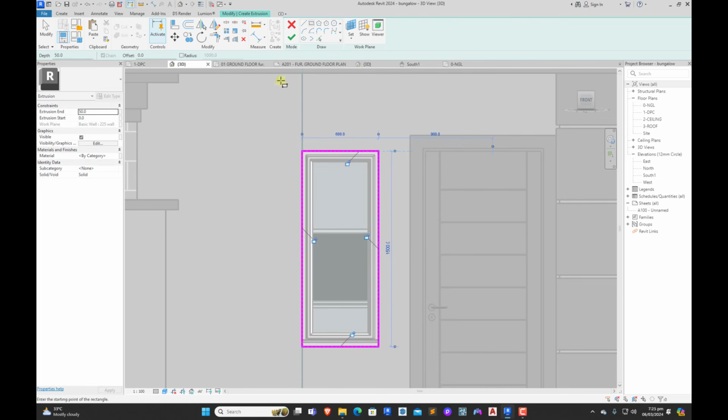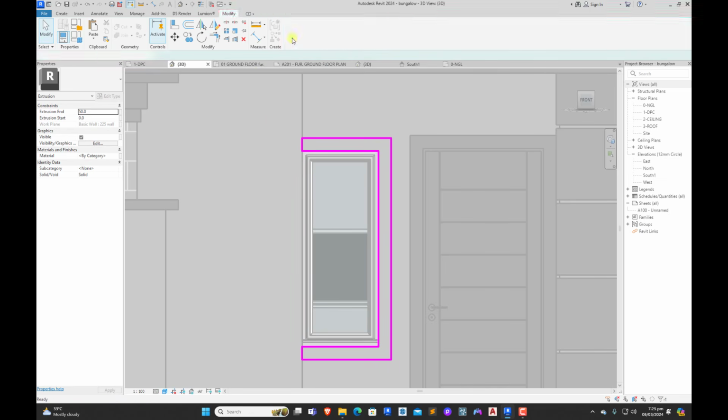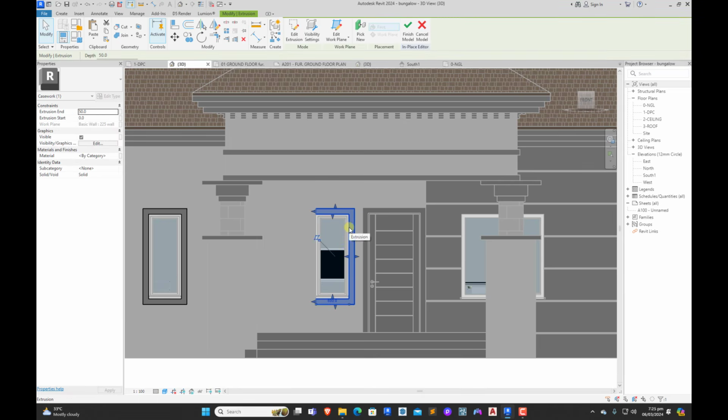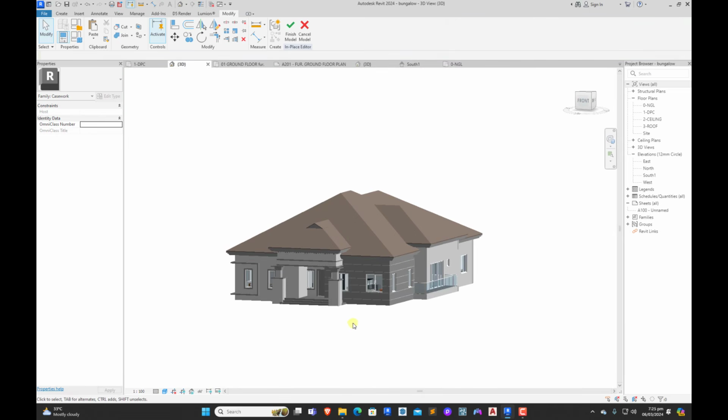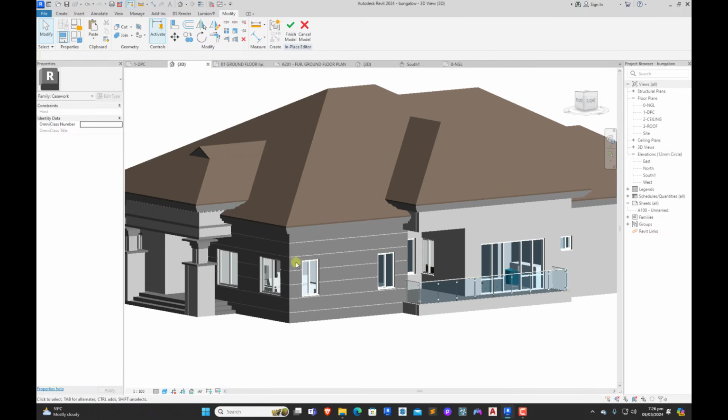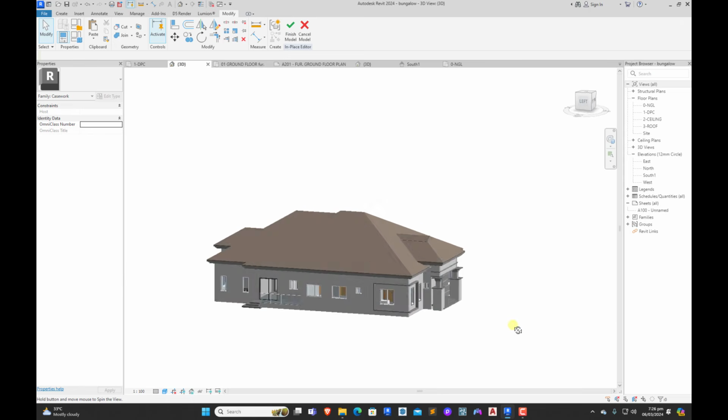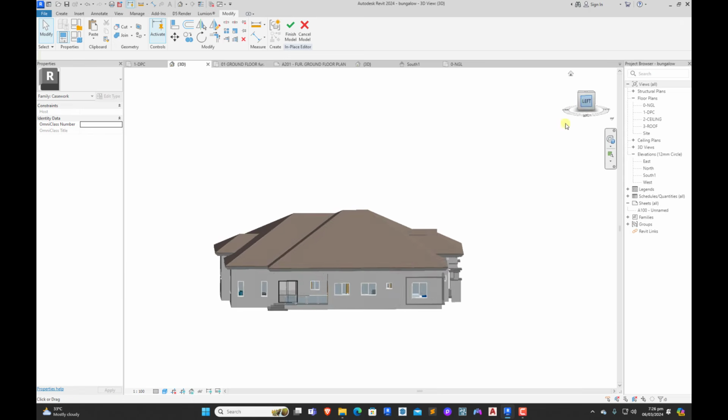So we have this one, and we offset our 100 mm. But this, we're going to trim this one this way, and also going to trim this one this way. We'll split this, and also trim this way. Delete this line. Alright, so that is one again. So we also do, okay, we're not going to add window hoods here. We're going to add some window hoods here, definitely.